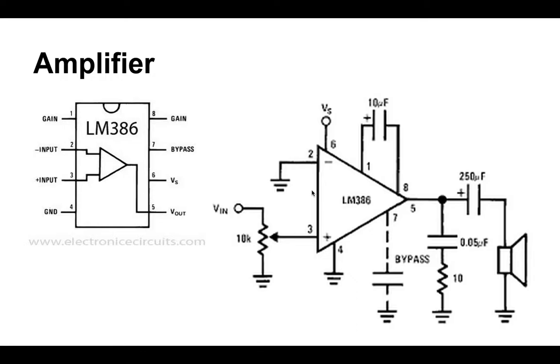If you look at the circuit, on the left-hand side is what you would find if you looked this chip up in a data sheet. This is actually what it looks like looking down on it, and you know which end is the top because it has the little cutout at the top. It might be a little hard to see on the camera, but if you look close, every chip has either a notch or a dot denoting what pin number 1 is.